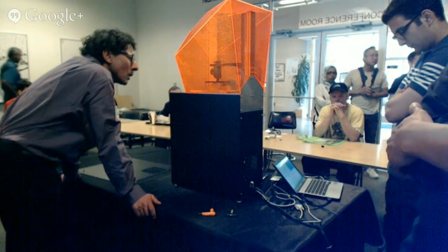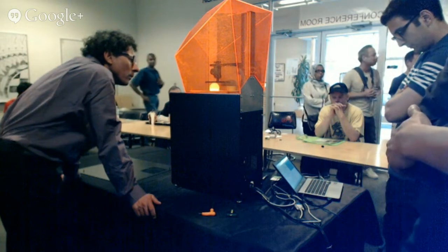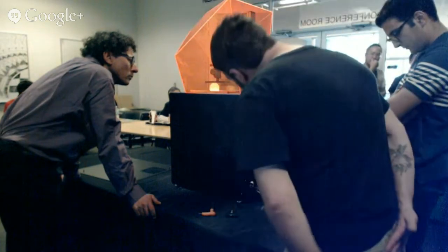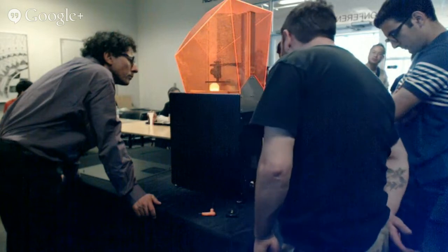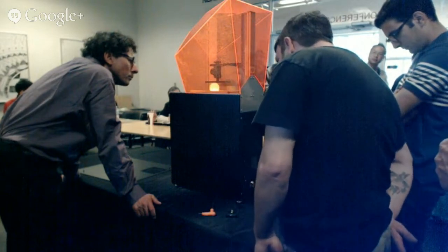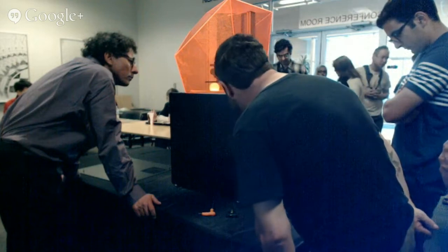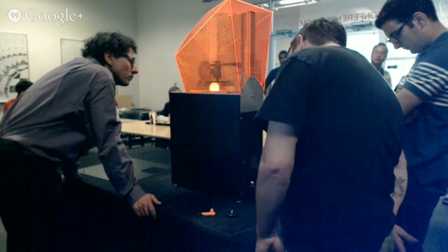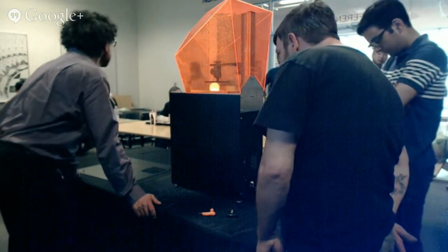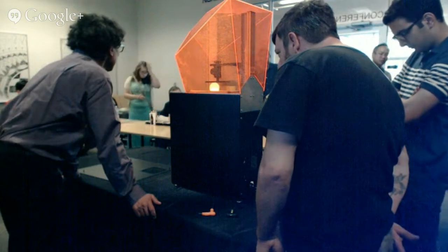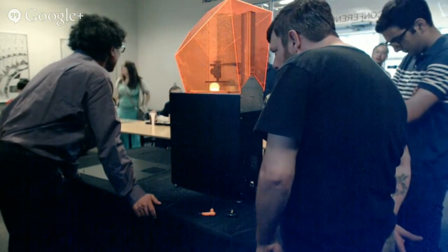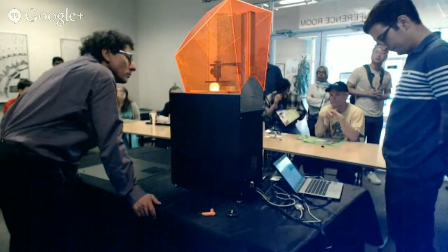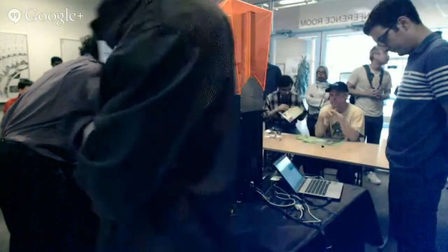there are some features of this printer that are different from traditional or other 3D printers, like the most one that everyone knows about. Teflon is a big difference. Teflon means that the vat surface is chemically indestructible. When I print on bare silicone, I mentioned that the resin reacts with the silicone. The resin especially reacts with silicone when you're shooting light at it and the photo initiators are acting, right?